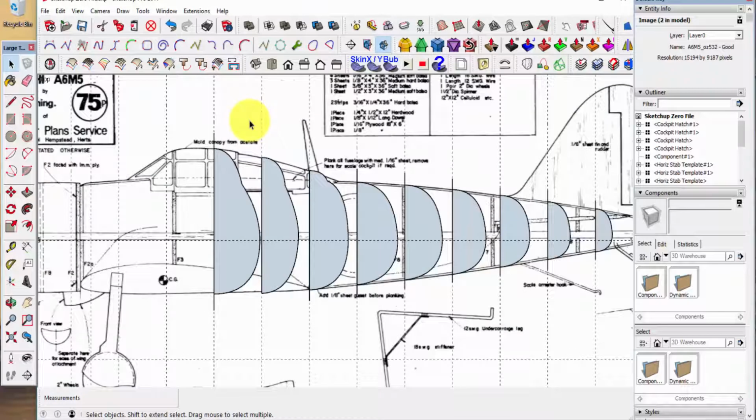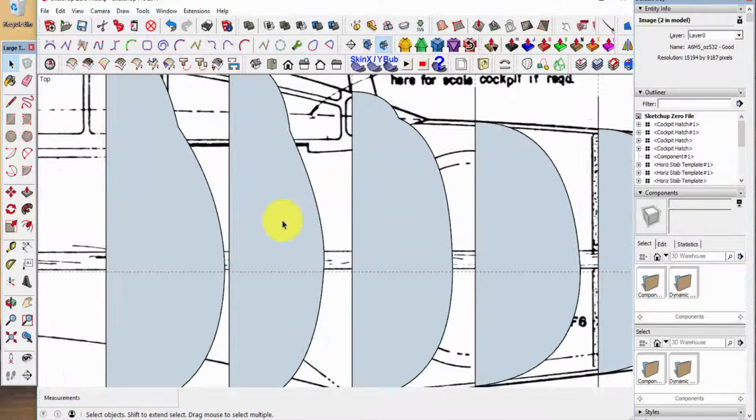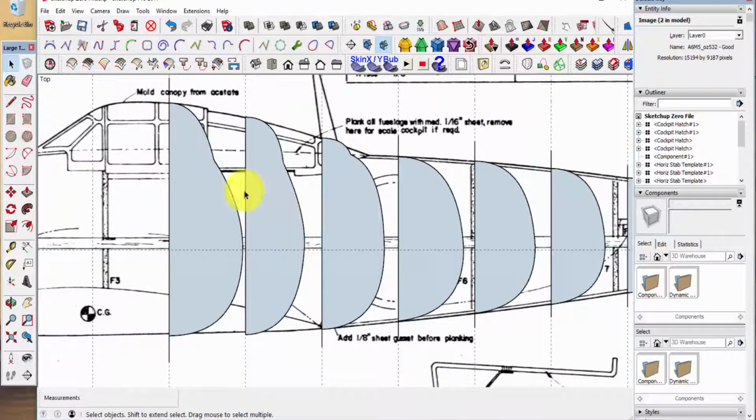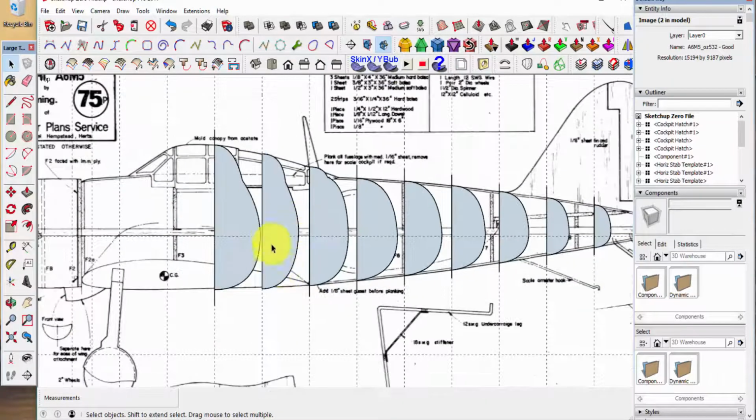Now we need to stop for just a moment and take a look at this. We're developing a problem here, and the problem is this. If you drop one of these drawings over the top of another one of these drawings, they melt together, and then you just have a real mess trying to straighten things out or moving it or sizing it or anything else. The way you have to get around that in SketchUp, now I can't speak for every CAD program, but the way you have to get around that in SketchUp is to create components.